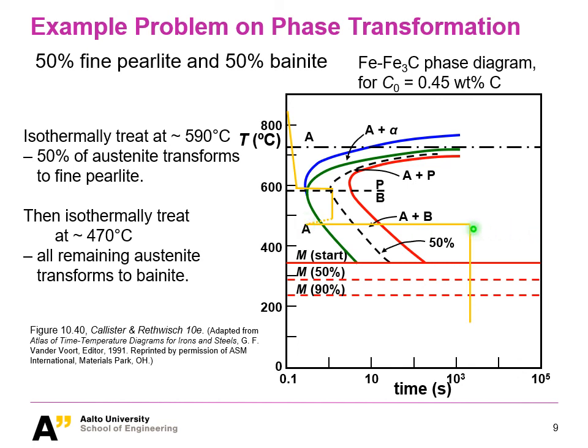And here you have completely comfortable carbon atoms in perlite, austenite, and bainite. They don't need to suffer from any oversaturation. So although you're doing a quenching, you will not have martensite. They are perfectly in a good equilibrium of bainite and fine perlite.